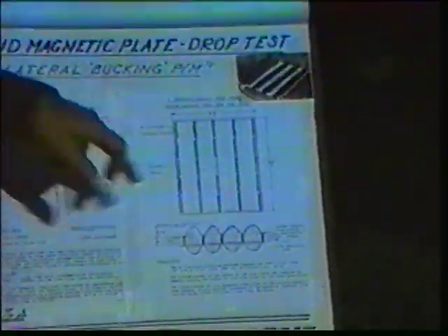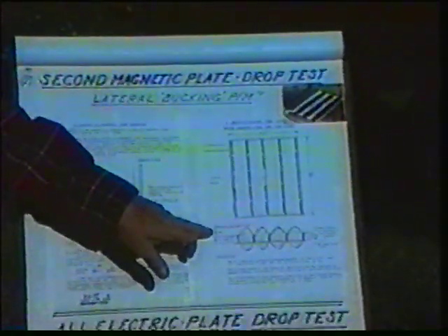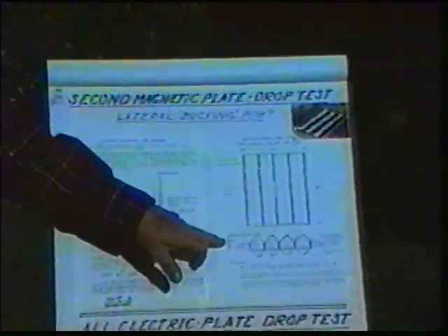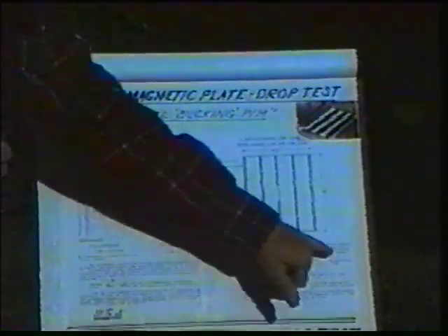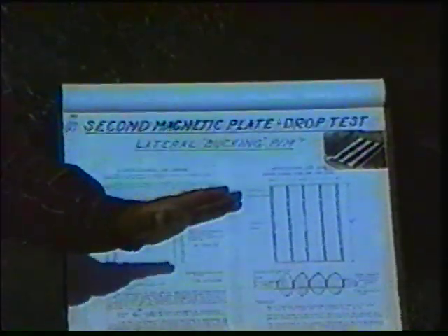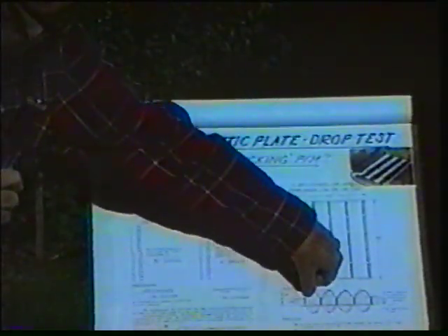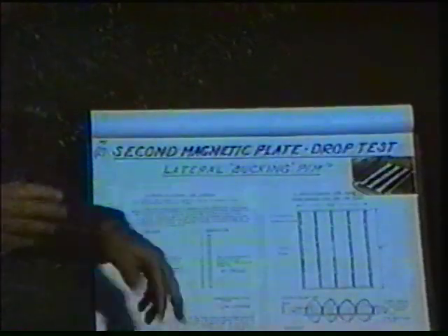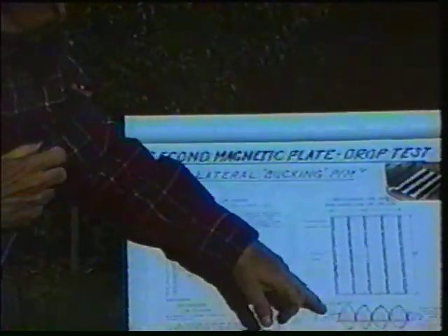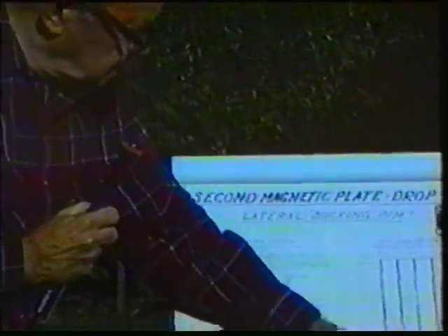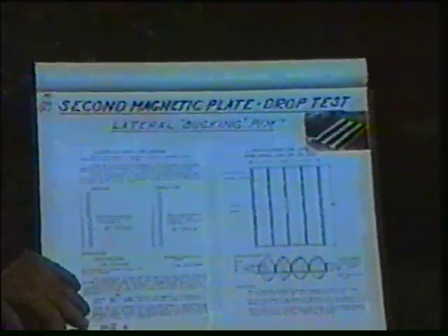So in this case, with this size magnet, the flux amplitude for this plate was 1.5 times. Now, normally, here you see at the ends would be the normal, unbucked magnetic flux. No amplitude. In other words, the magnetic flux from a flat magnet like this just goes right out from the face. It's not impeded by anything. But when you buck them, the magnetic flux pattern bows out. Now, the upshot of this is the other one was 14%. You do it this way, you get a 31% differential. And it's logical that you would expect that.